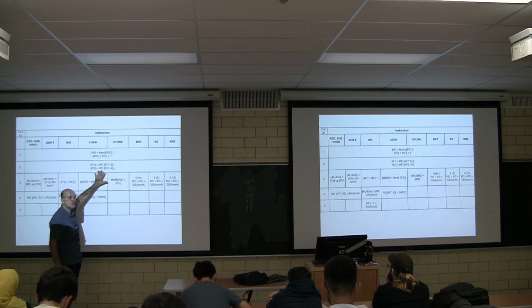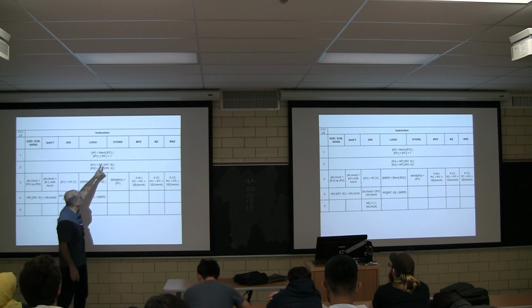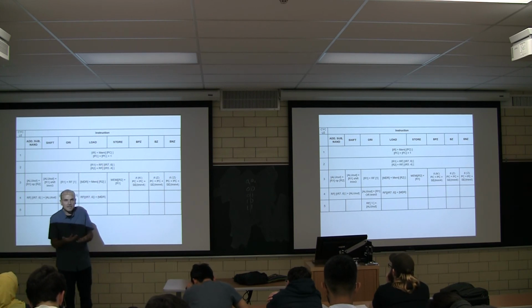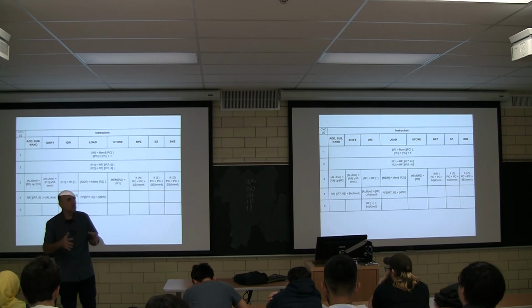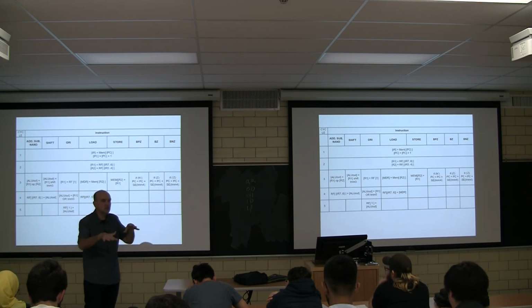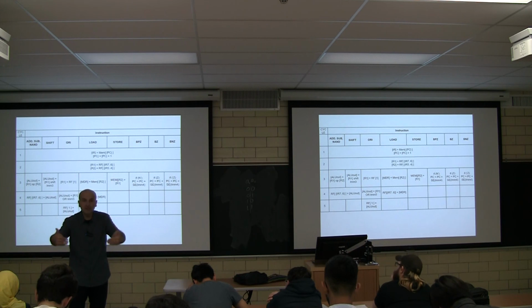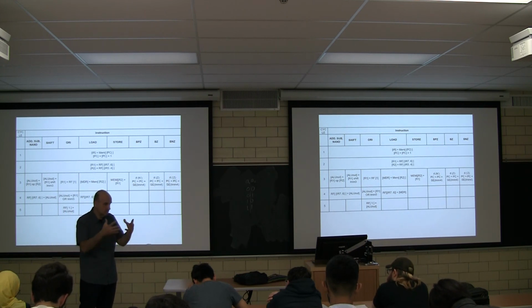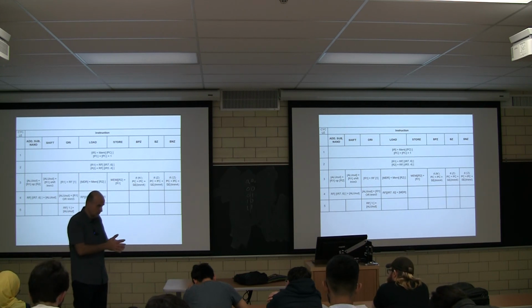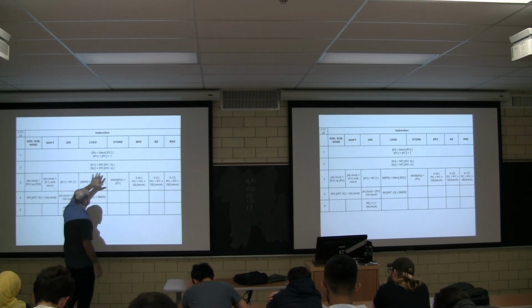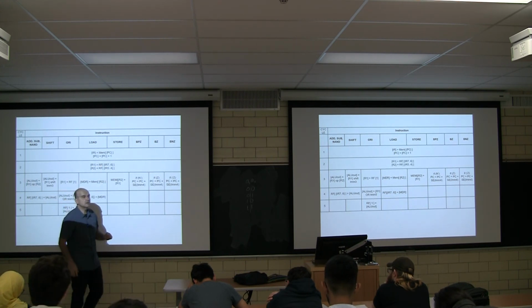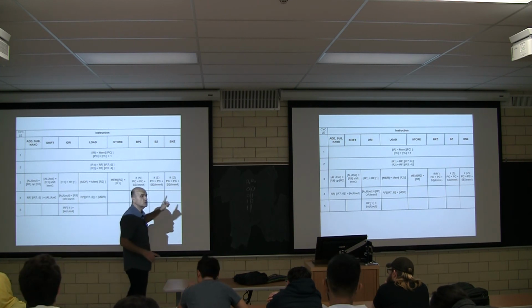It's not going to be super obvious in the beginning, but let me point this out. What's happening here is the control is looking at IR. The control is looking at IR and is trying to decide what should be my next step. So we're going to assume it's going to take one cycle to decide how to set the control signals for cycle 3. Okay? There's some time that the control needs to look at those. Now, this could have been empty. We could have said, let's do nothing. However, notice what we're doing over there.